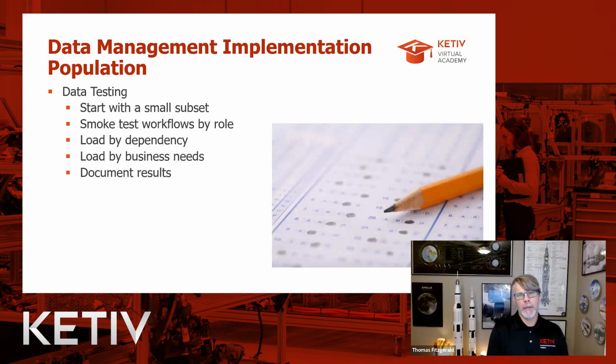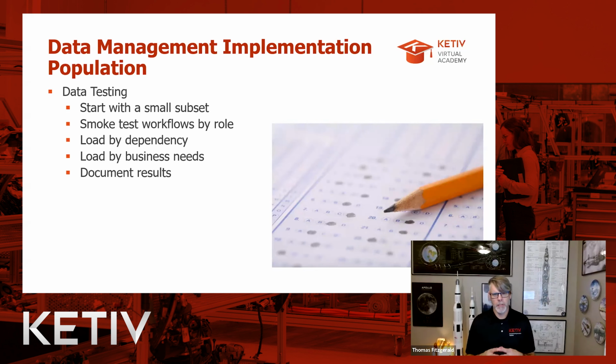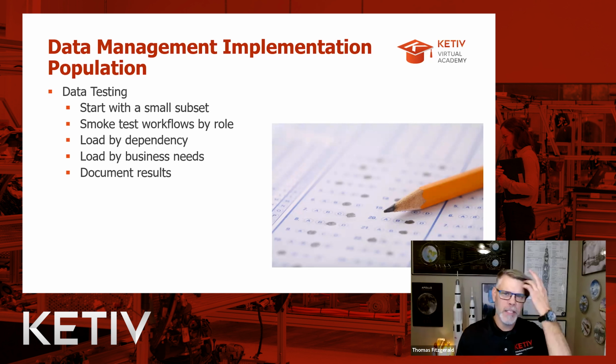Now, the last thing that we want to talk about here when it comes to taking information that doesn't exist in your PDM and getting it populated up into your PDM is testing. So I showed you a number of different ways that you can get information into your system. But before going full bore and just loading everything that you possibly can, start out with a small subset.